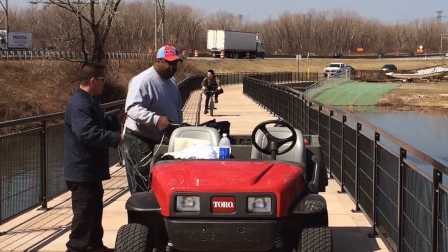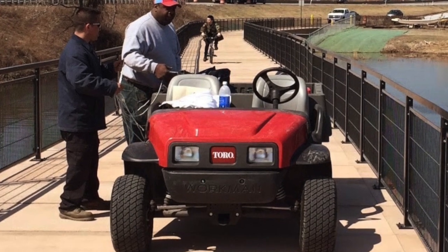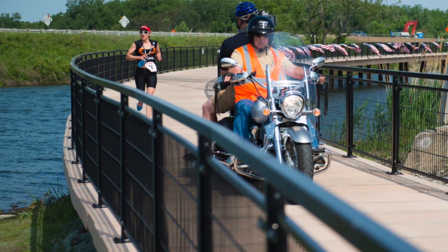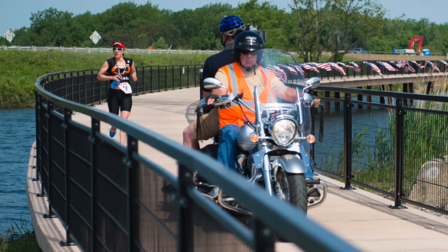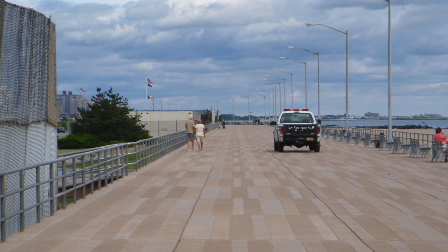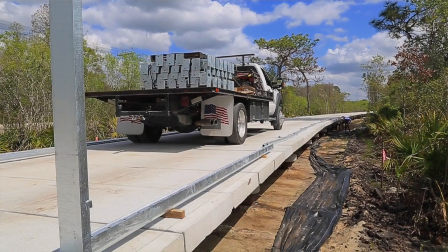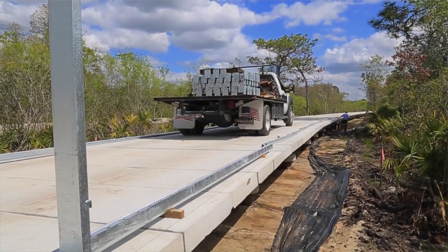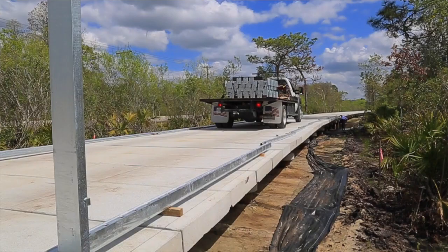Next, as the boardwalk itself gets wider, you may have to design for vehicular loading, and whether that's a maintenance vehicle or is simply a small pickup truck, or in some cases an ambulance, emergency vehicle, those can become quite substantial loading, vehicular loading.